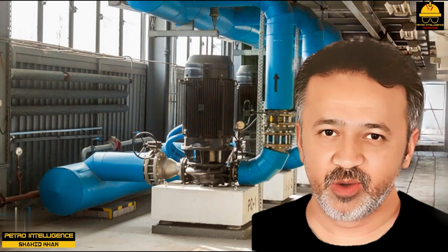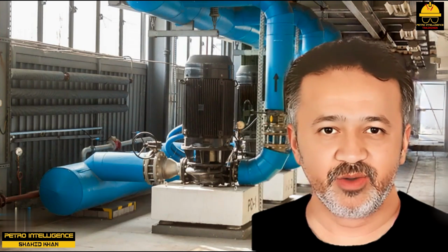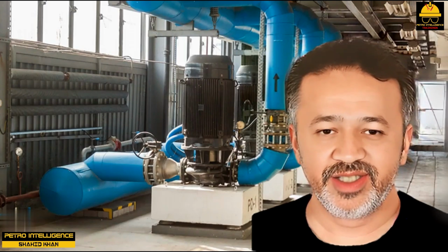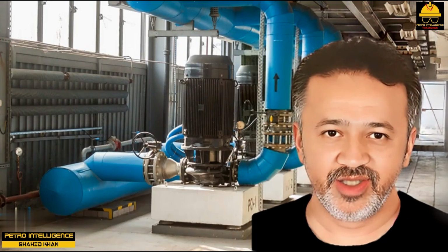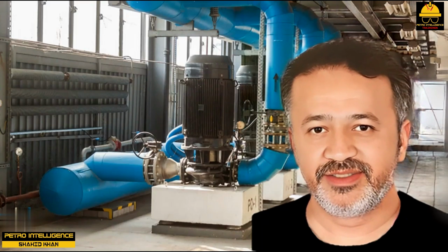If the pump is developing 1000 psig of differential pressure, cooling the liquid by 200 degrees Fahrenheit will increase its discharge pressure to 1100 psig. If the discharge control valve is now opened, the pump's discharge pressure will drop back to 1000 psig as the flow increases.